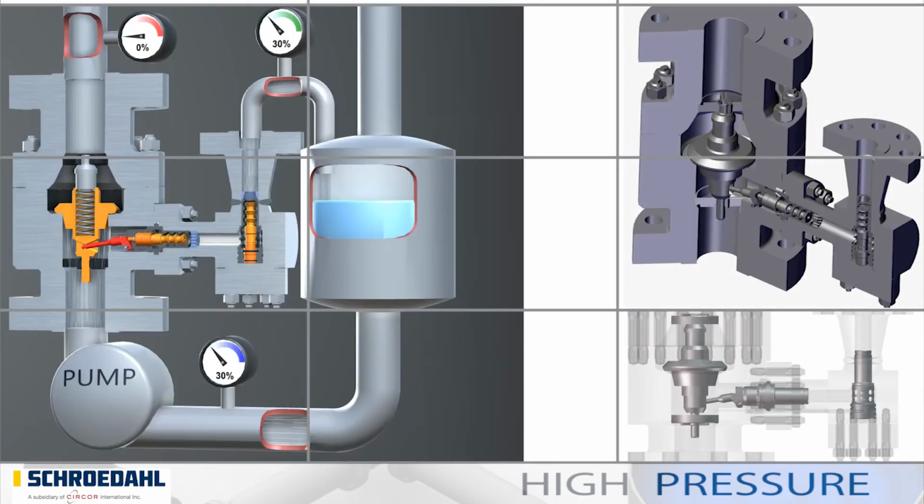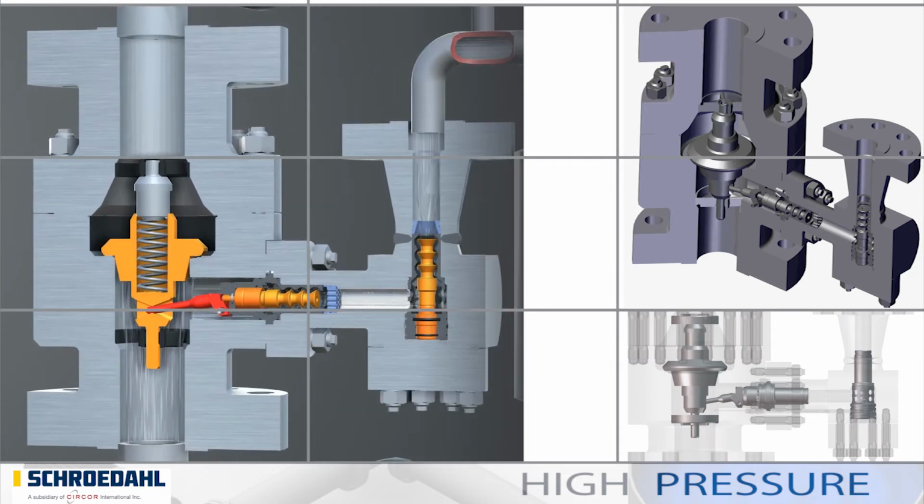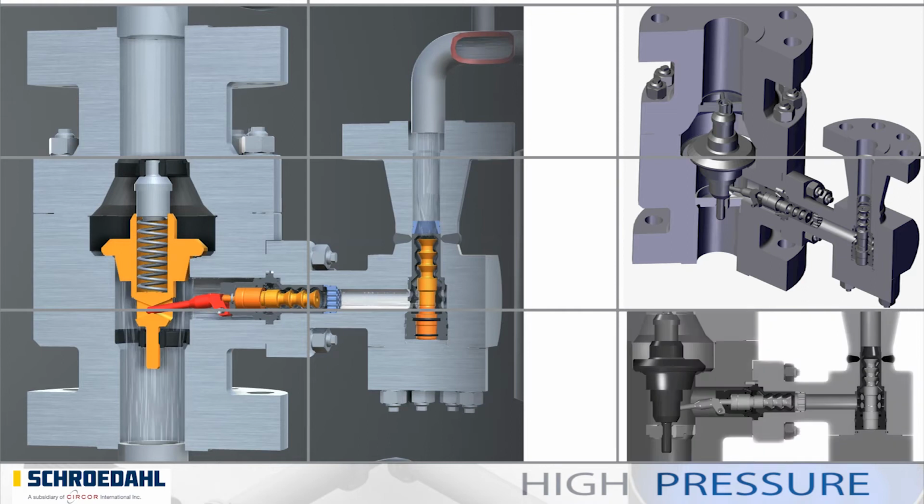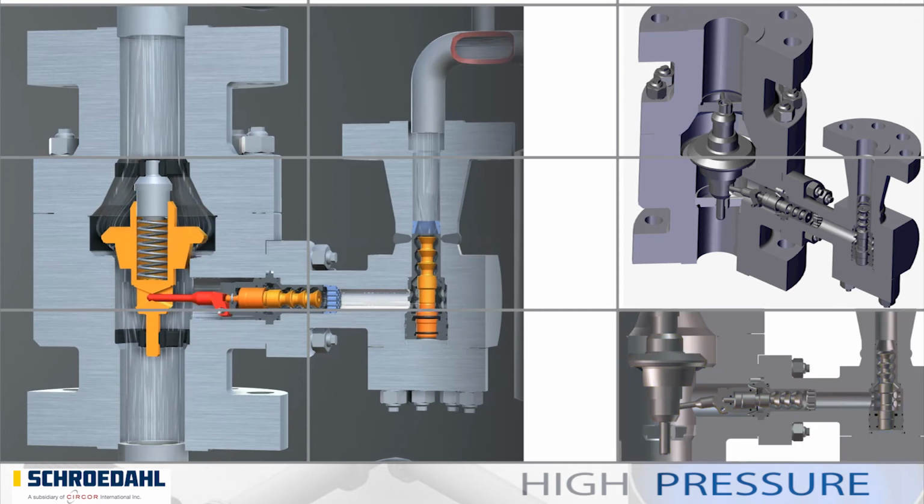If no process volumes are extracted, the main check valve is in the seat, and no further medium flow to the receiver occurs. The automatic recirculation valve is open to the maximum, and this supplies the volume required for every speed. The pump can keep running even if the process is not extracting any media, the required minimum volume being discharged via the bypass system on the MRK. The minimum process media conveyance remains active, which means that the unnecessary and fault-causing stopping of the pump does not occur. The MRK functions as a modulating unit right up to full load.